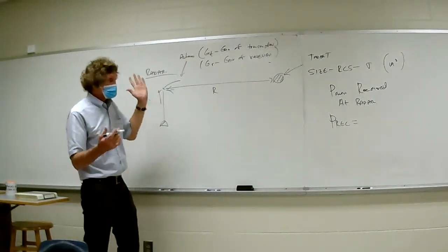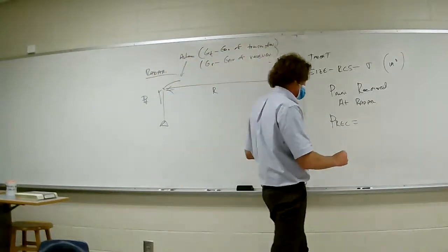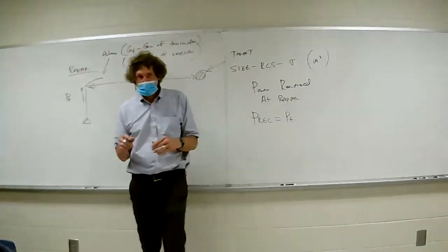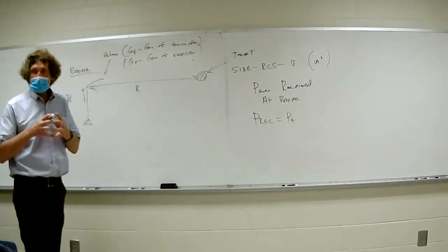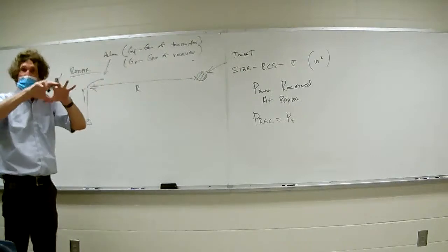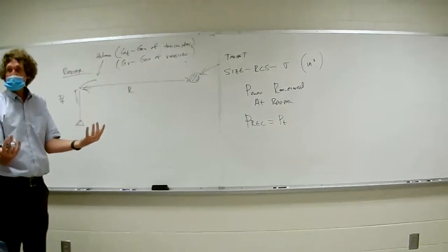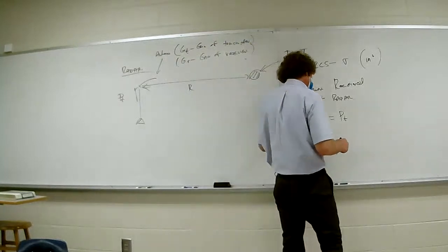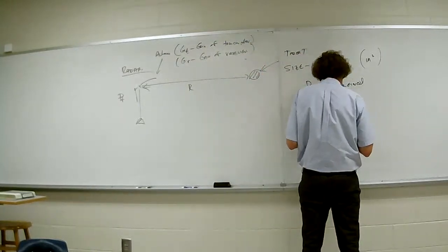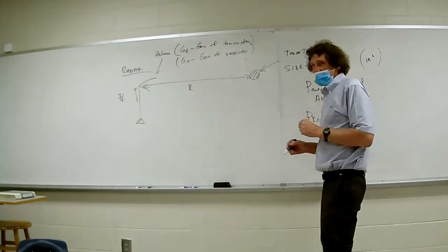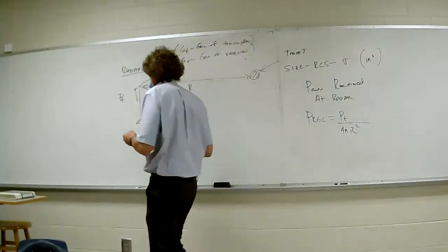First, you take the total transmitted power. Just put it down. You know the power received has got to be proportional to transmitted power. Next, when you transmit that power, it spreads out as 1/4 pi r squared. That's the surface area of a sphere. Y'all follow me? So this is if there was no antenna, we're somehow able to blast things away with no focusing ability. That would be the power density that's being launched out there.